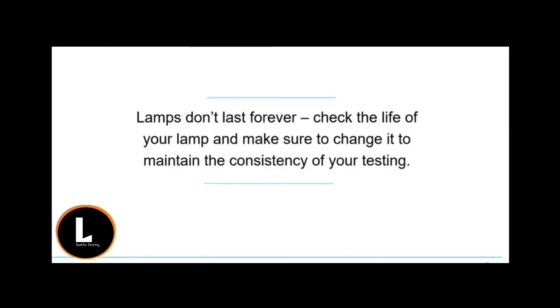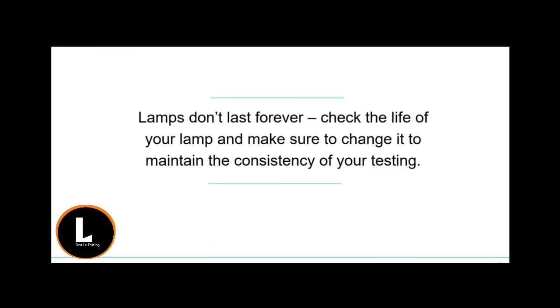Something else to keep an eye on is that all xenon arc lamps have a lifespan, and towards the end they will become less bright. Some instruments, like our True Fade at James Heal, will actually be set up to compensate for this by adjusting the power to increase the brightness, but there ultimately comes a point when the irradiance can no longer be maintained and the lamp must actually be changed.